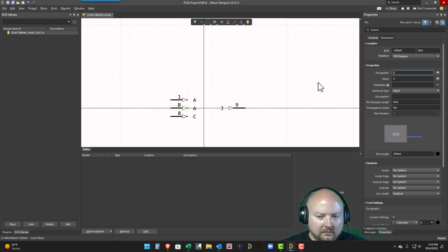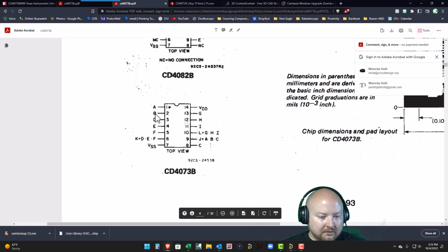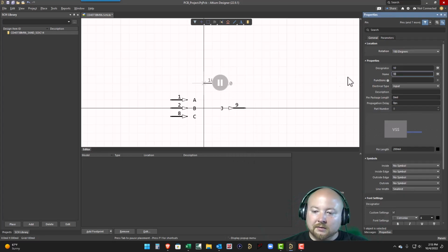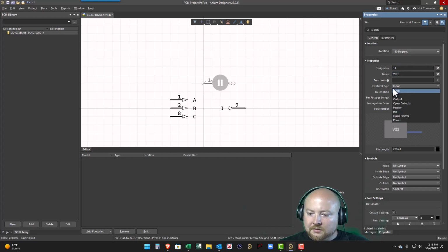Whoops. The name is B. The designator is 2. So pin 1, 2, and 8. 1, 2, and 8. All right. And now the power pins. So PP for pin again. Place pin. Tab. Come over here. Designator is 14. The name was VDD. And electrical type is power.